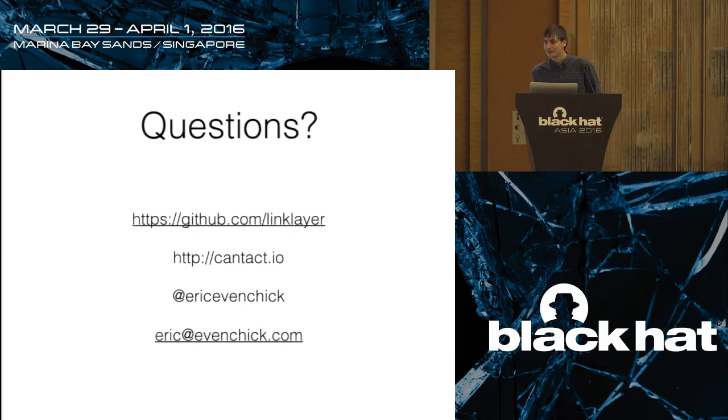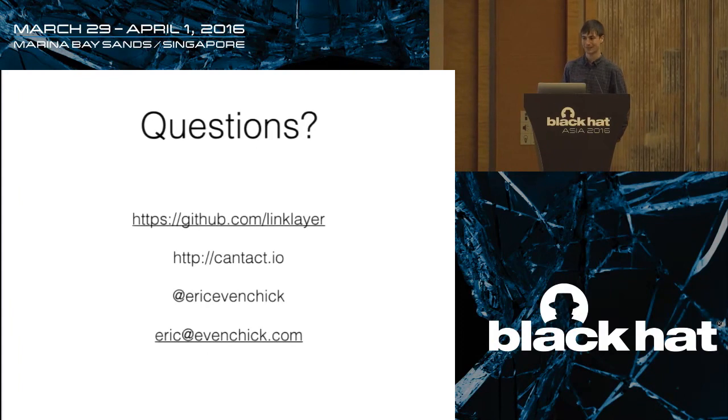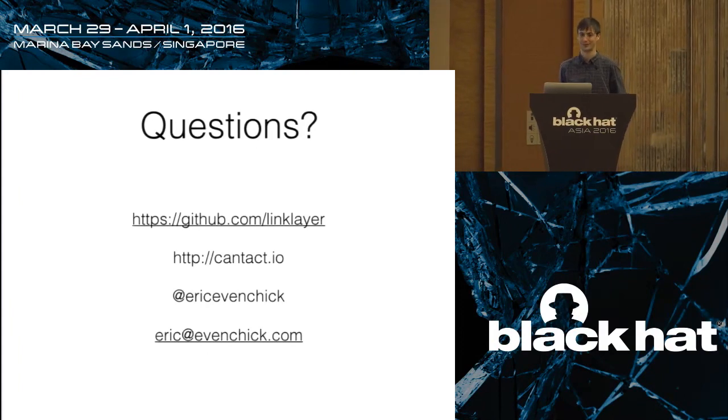Yes? Eric, so it's known that Bosch like to stop you from tampering with the hardware, so encasing a lot of their relays is not really present. Do you foresee manufacturers doing this with the CAN bus in the future? In some ways, hopefully. There are physical attacks that there is history of, where you can be outside of the car and get on CAN because you smash a tail light or you get onto the power steering pump or something like that. These are not physically in the car, and from there you have access to a CAN bus. And like we said, it's just a big bus. There's no switch. In a lot of cases, you can't identify where traffic's coming from. So physical security will definitely be part of it.